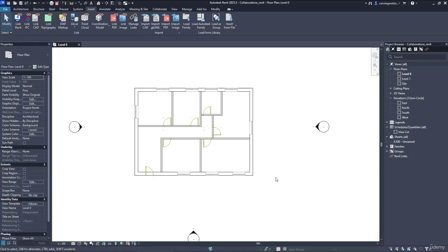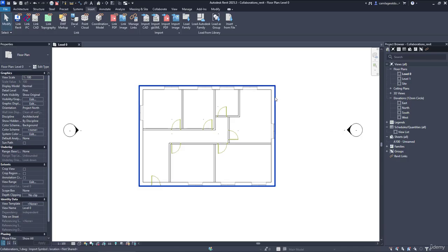If the architect has to change the CAD file for any reason, with this option Link File, the CAD file is updated in Revit automatically. If you are familiar with AutoCAD and know how the external references work there, it's a similar process. Another advantage, this method also helps to keep the Revit file smaller, since the CAD file is not directly attached.